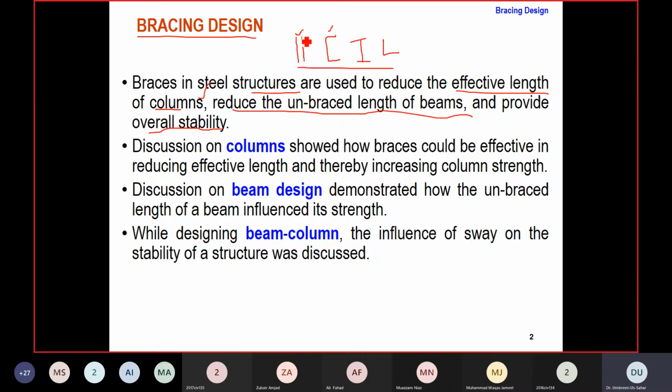For all of these you need the area of the brace. That will be the design parameter we are going to calculate today, and the area of the brace depends on different factors and parameters we will discuss here. Finally, for the rod kind of bracing, simple diameter is required, so from the area of the brace you can calculate the diameter. According to the steel strength, the yield strength given to you, you are going to provide the steel for the bracing.